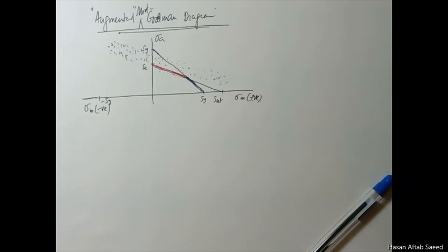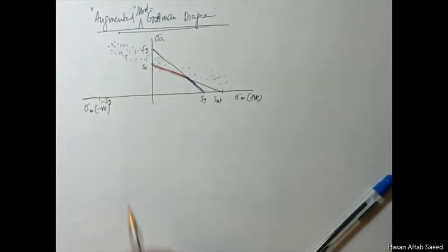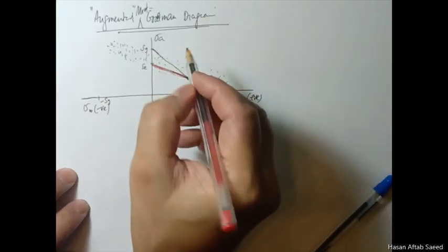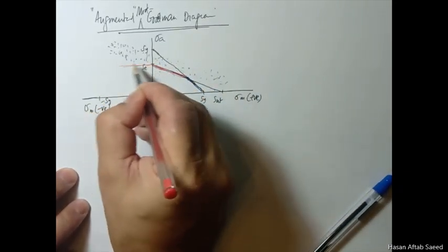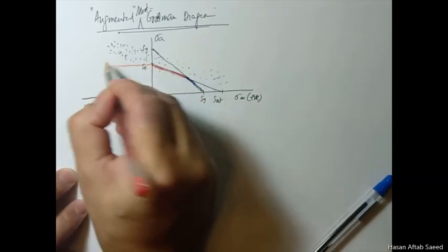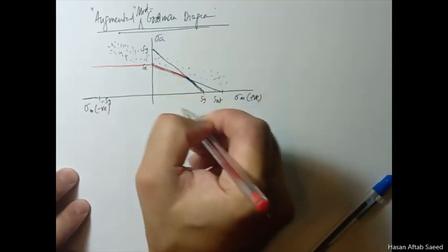But what we actually do is we don't rely on this increase to make our life somewhat easier, and because it is on the safer side also, we just assume that the fatigue life is unaffected by the negative mean stress.